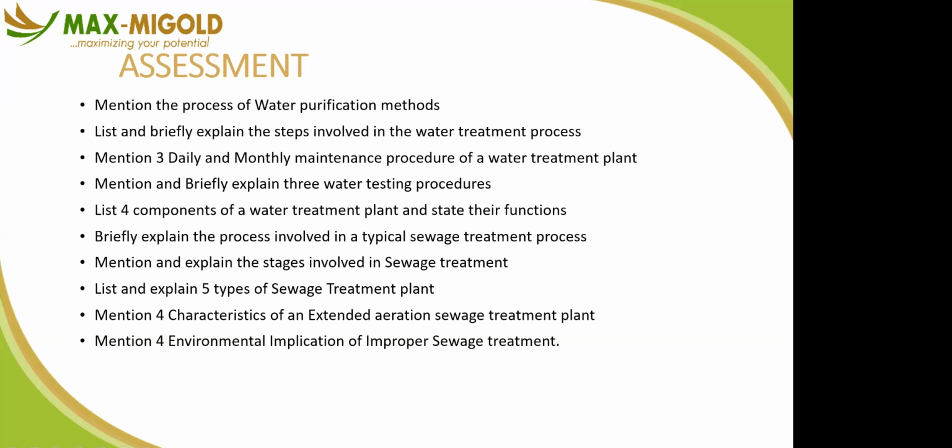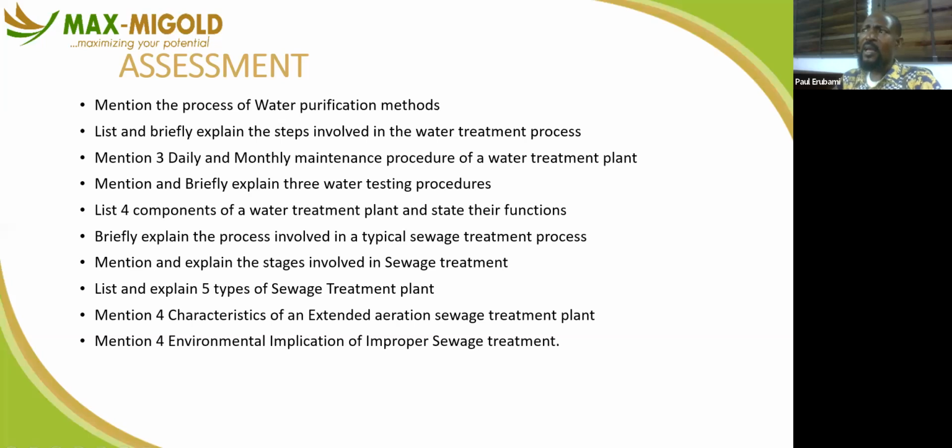If you don't have any blockage, there's no need, because at times when you consistently open your manhole, if you don't do proper cementing after you open it, most especially when you open it today and say you are going to do the cementing tomorrow, between today and tomorrow, overnight, a lot of rodents and ants will have found their way inside that manhole.